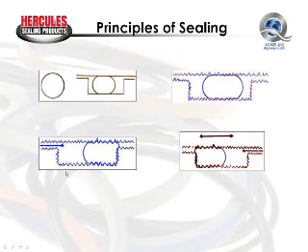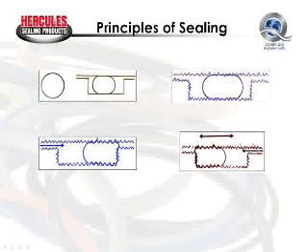However, in dynamic sealing, we have relative motion involved. We may have flow coming from alternating directions. First, you have flow from the left side. You have flow from the right side. You actually have the seal moving back and forth in the gland or in the groove. Then you have a surface moving across the seal. This is our relative motion that's involved in the seal.